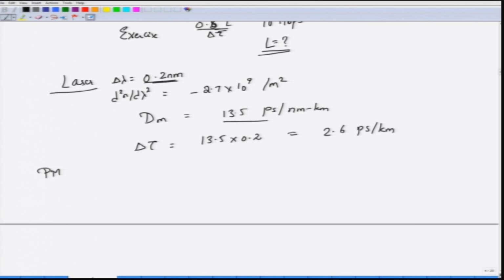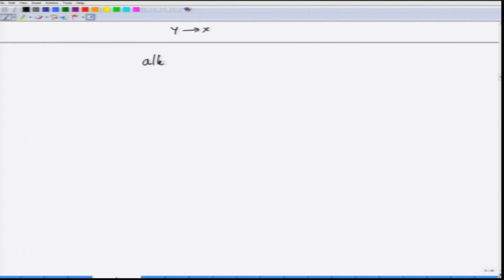It is time to wrap up dispersion and then go to another factor which is called attenuation. Okay. Attenuation, again, the mechanisms whereby attenuation occurs in fiber can be intrinsic, and this intrinsic includes absorption and scattering of light, and it can be extrinsic. Extrinsic factors such as bending, stress, etc. can cause attenuation. We will not consider this attenuation now, and we will of course not even be considering the full picture of why attenuation occurs. This is something that is best left for material science people to explain better.